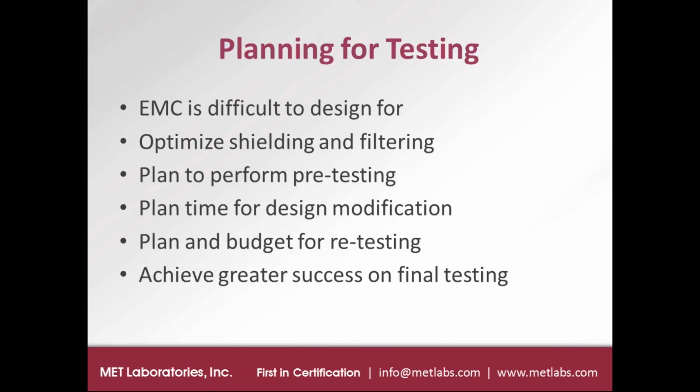So EMC is difficult to design for, meaning it's difficult to design to pass and have a high level of confidence of passing tests simply based on design concepts. So there are best engineering practices that can be followed. However, there's a high failure rate for several of the MIL Standard 461 tests in almost every project that comes through.